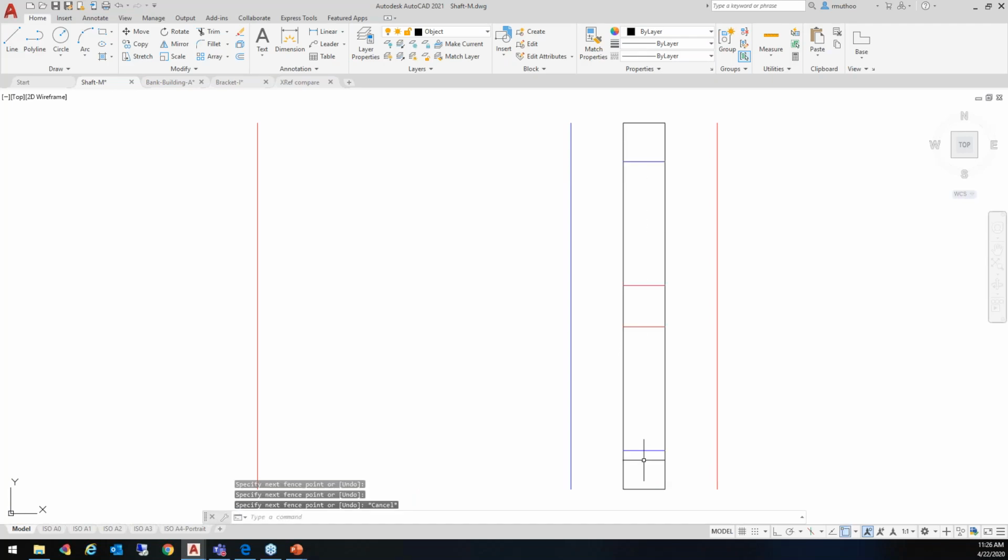So let's go escape. And then we have, as I told you before also, the third default option, the freehand selection option. So for example, you wanted to trim this line between this and this area, and then this line and this line between this and this area. So for that, we'll start the trim command again, and then holding the mouse button, you don't leave the mouse button.